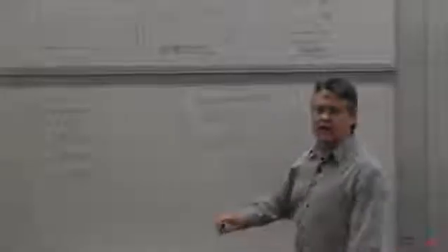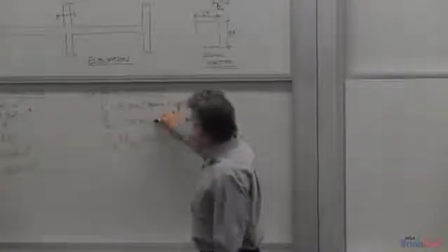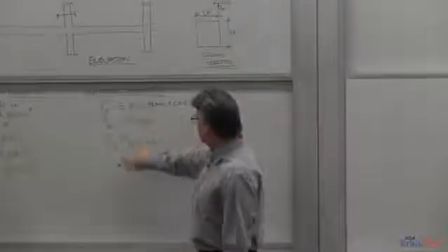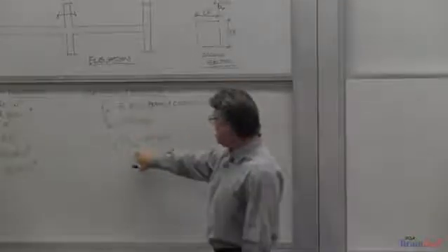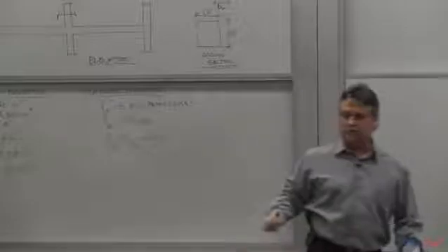The material properties: we both have 5 KSI this time, concrete beams and columns. The tendons are 270 KSI, and both the longitudinal steel and the stirrups are 60 KSI. So we are both being asked to determine the pre-stressing force and drape in both spans.